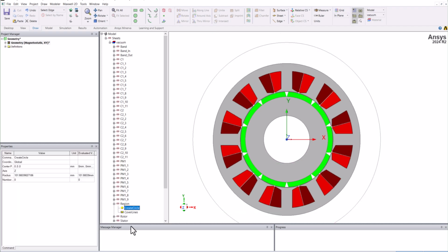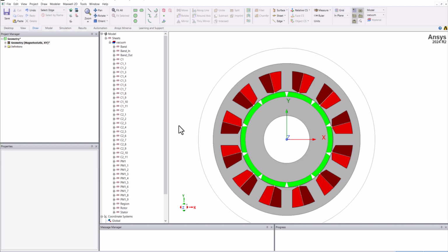One extra thing you can do is, if your stator OD is also going to change in your geometry, you can parameterize the region also, like stator OD by 2 times 1.1. Generally you can keep 10 to 15% of extra space. I would recommend keeping between 10 to 20%, whatever feels okay to you. This is purely the user's choice, but 10 to 20% is a sufficient margin. We're going to save this, and now our geometry is completely ready.